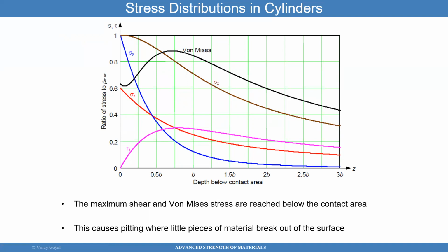If the body of material behaves brittle, like some ceramic materials, and the ball or the cylinder was brittle, in those scenarios the failure criterion that most likely is applicable is the max principal stress. And that's going to happen more at the surface of the material, where you have the highest stresses.